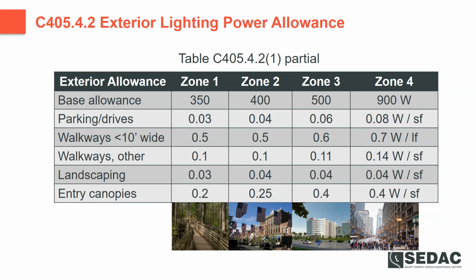Zone 4 is only for high commercial activity in a major metropolitan area as deemed by the local zoning commission. For the state of Illinois, Zone 4 would only be found within the confines of the city of Chicago, and predominantly only for things such as State Street or Michigan Avenue. So the vast majority of projects you're looking at are Zone 2 and Zone 3.